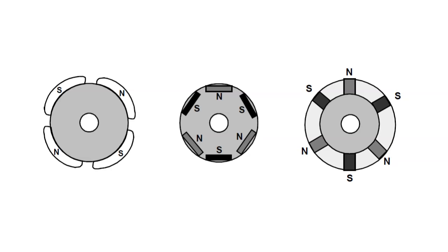In brushless DC or AC motors, we have three types of rotor. One of them, on the left side, is surface mounted. The second one, you can see, is the interior rotor type. In this type, permanent magnets are mounted on the interior side of the rotor. This is called rectangular magnets. And the last one is a rectangular magnet inserted into the rotor core. Okay, generally in the industry, we will see three types of rotor shape.